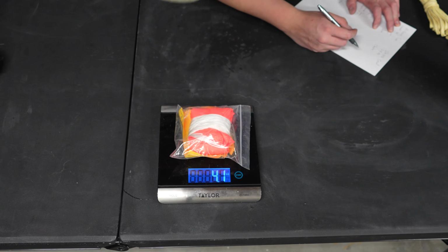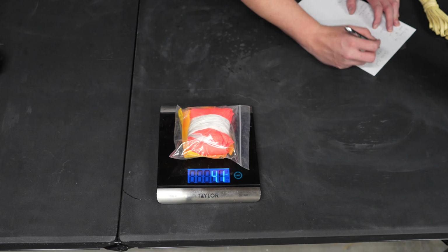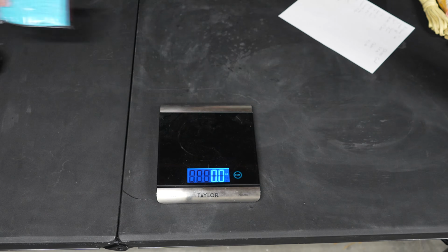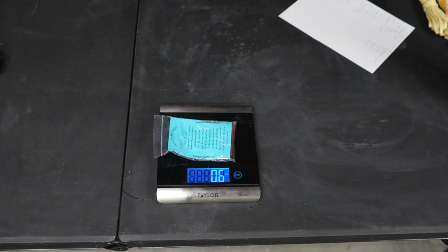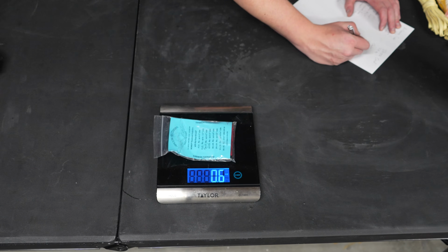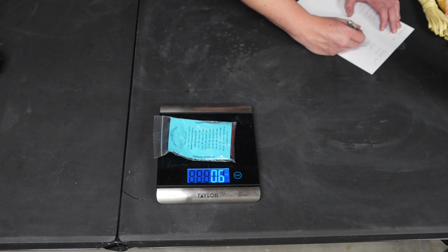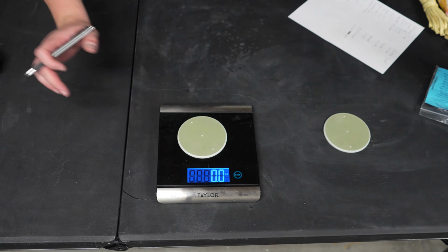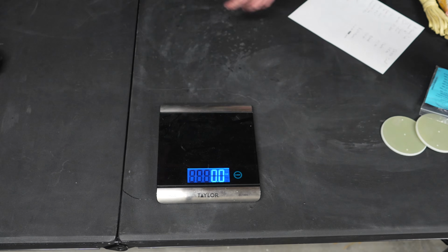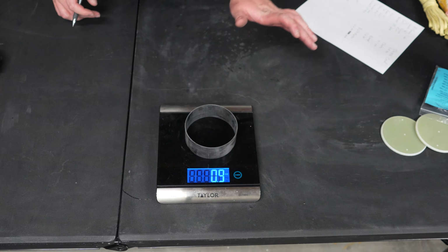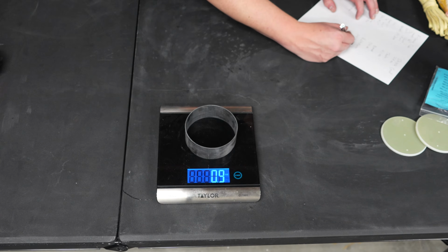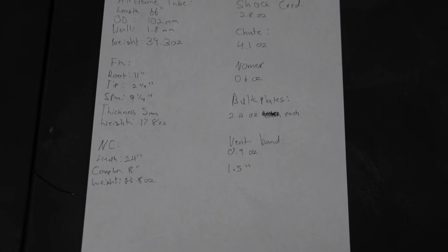One thing to keep in mind about this rocket in particular is that it's minimum diameter, so I don't have a motor tube assembly to worry about here. But if you do, be sure to get accurate measurements of the motor tube's weight and the centering ring's weights as well, and only measure the portions of the fin that will be outside of the airframe. Don't include the through-the-wall fin tabs. And that's it. It really is that easy.